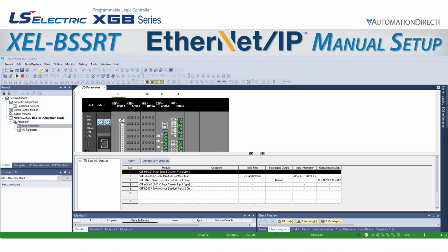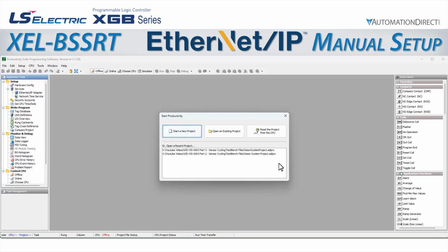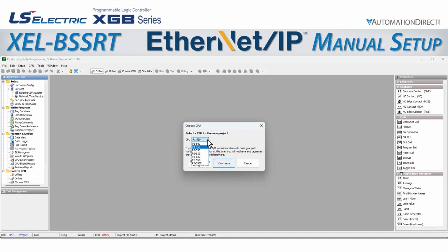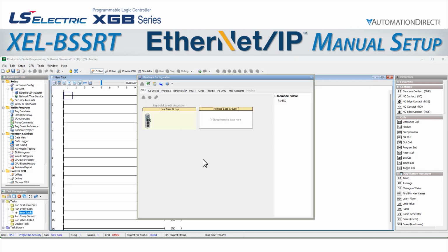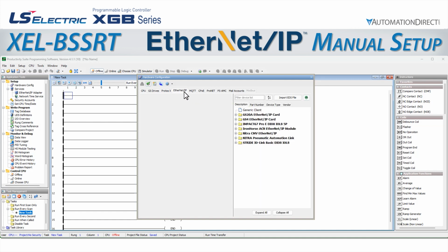I will open Productivity Suite version 4.1.1.10. We will start a new project and select the P1 550 as our PLC. We can then click Go to Hardware Configuration. It creates a new project and opens the Hardware Configuration window. If we go to the EtherNet IP tab, on the right side is the EDS file library.